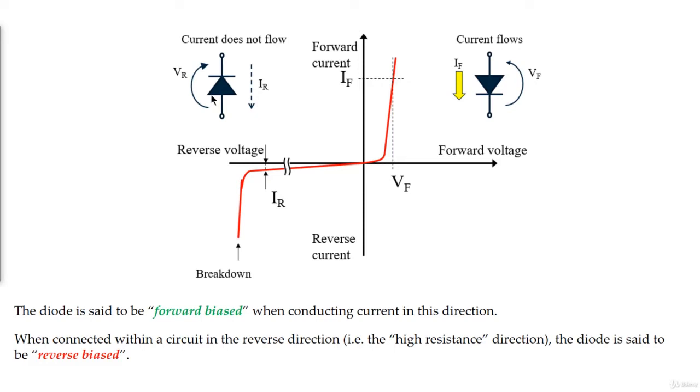So a diode only blocks current in the reverse direction, for example when it is reverse biased, while the reverse voltage is within a specified range. When the reverse voltage passes a certain voltage, as you can see here, the reverse barrier breaks. So the voltage at which this breakdown occurs is called the reverse breakdown voltage. When the voltage of the circuit is higher than the reverse breakdown voltage, the diode is able to conduct electricity